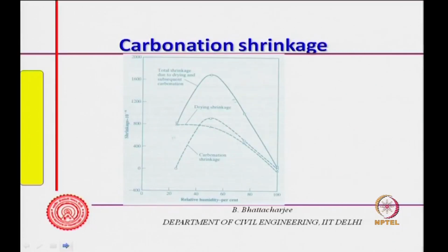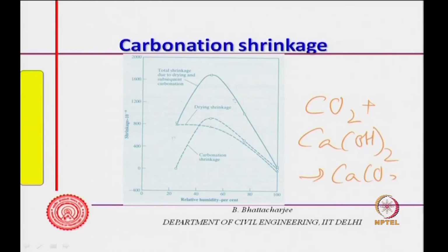Now, carbonation shrinkage occurs. Carbonation is a phenomenon where carbon dioxide from the atmosphere reacts with calcium hydroxide to finally form calcium carbonate plus H2O. We will discuss this a little bit later in the context of durability, and this product occupies less volume than the original calcium hydroxide. In presence of water, all this happens.